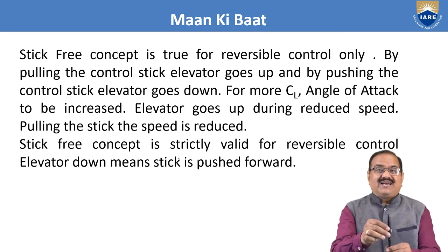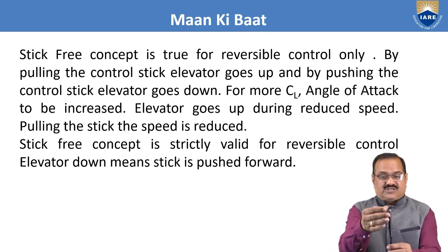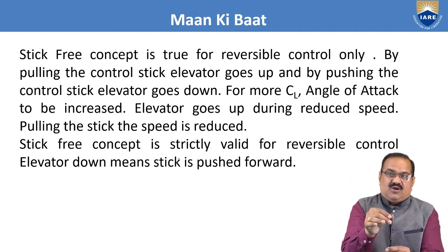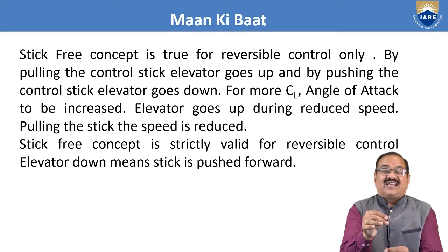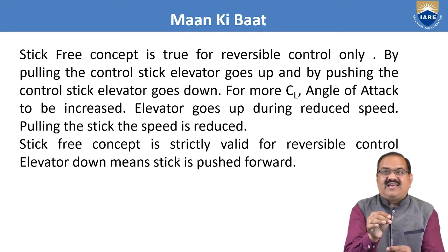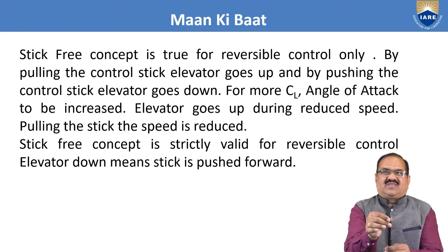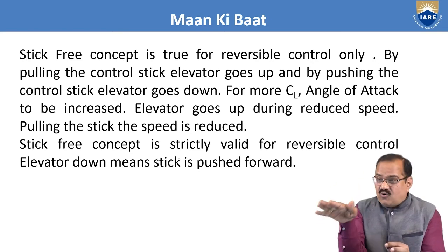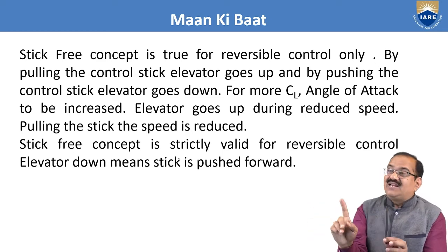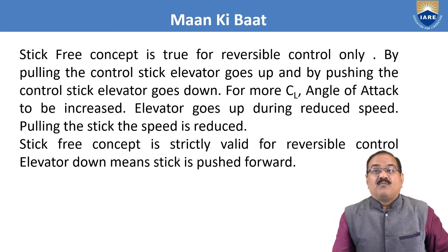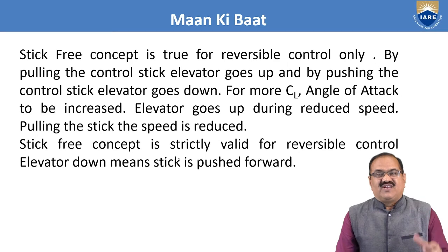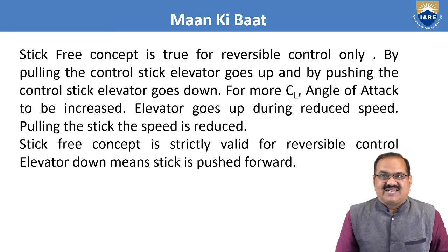By pulling the control stick, the elevator goes up, and by pushing the control stick, the elevator goes down. Elevator down will generate upside lift. For more CL, the angle of attack has to be increased.